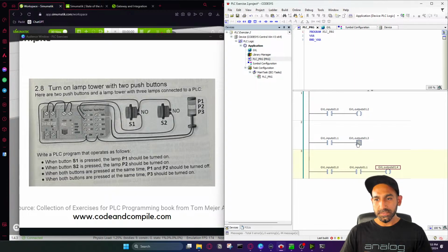But when both are pressed, these two should be off. So kind of like an interlocking. So what you can do is you can interlock these inputs and put their negate function here. So its negate function here and this negate function here. So they can turn off each other's. So in this case, I can have here a contact and make it negate and change its address to 1. So its NC contact is here, and NC contact of this input I will connect here. Negate.